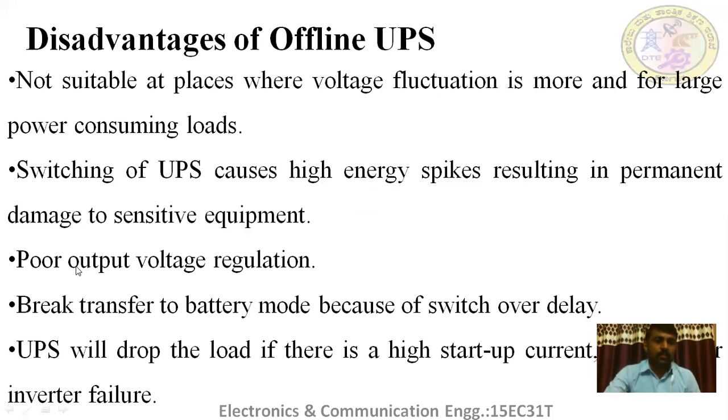The next is poor output voltage regulation. As compared to online UPS, the regulation of output voltage in offline is very less, or there are some fluctuations. The next is break in transfer to battery mode because of switchover delay. So this delay depends on the time taken by the static switches to change their source from mains to battery, or by the time taken by the user to initiate.